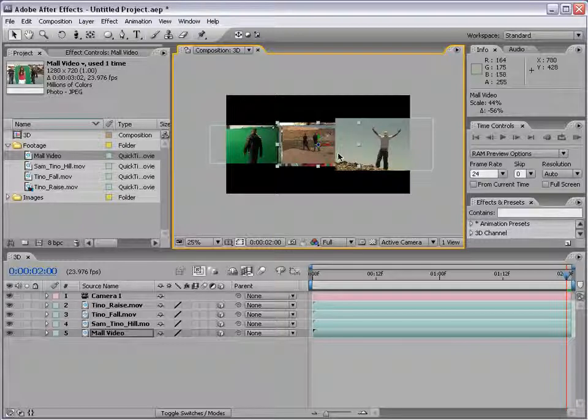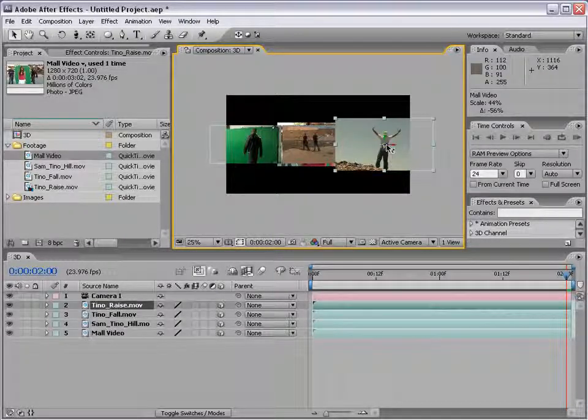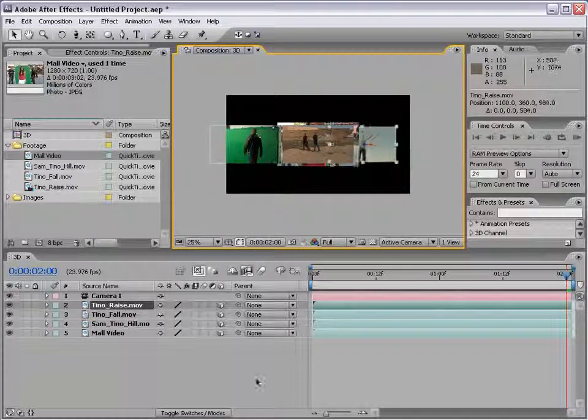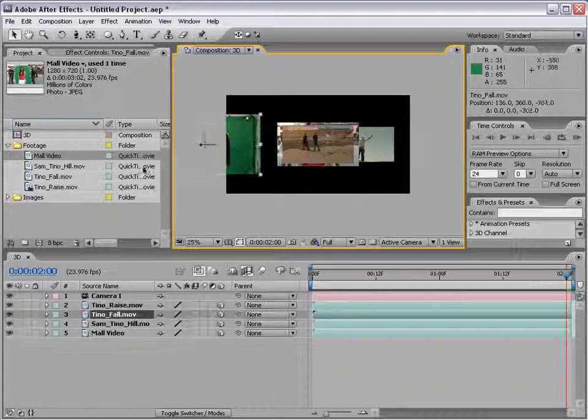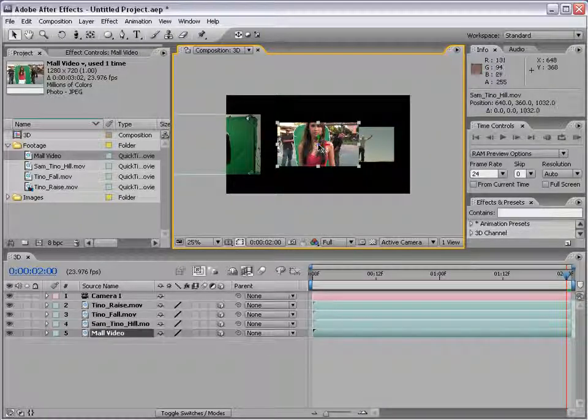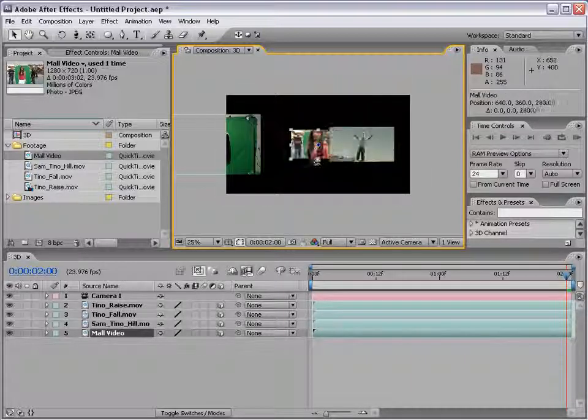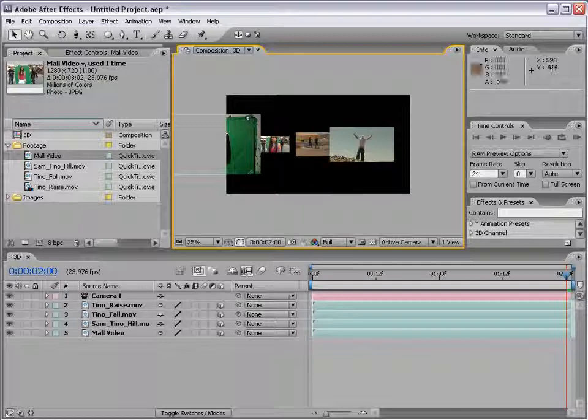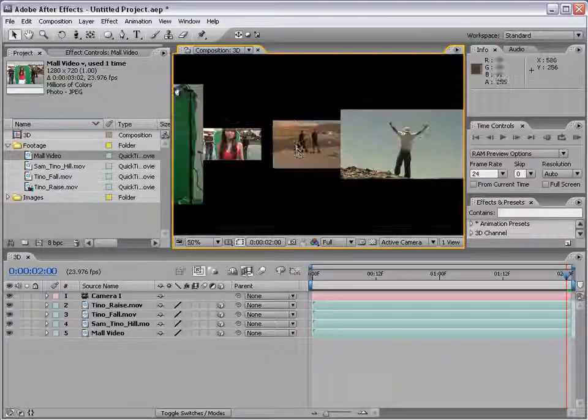Okay, now I can also move these layers forward and back. So I can go to the Z-axis, roll over until we see the little Z, and push this back. Take this one, we'll move it close, move this one back. You can also hold down Shift and it'll move the layer faster into the distance. So now we have our layers kind of offset in 3D space.